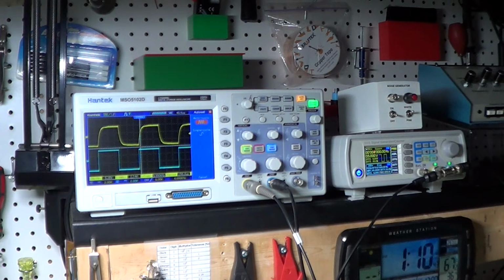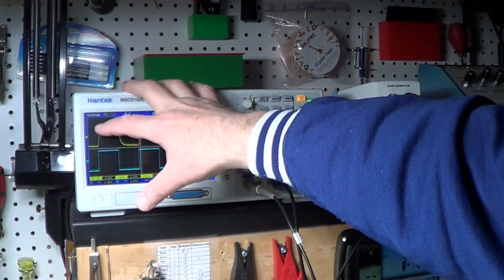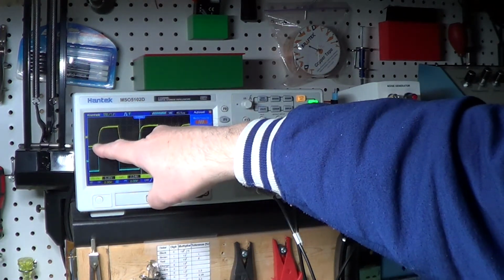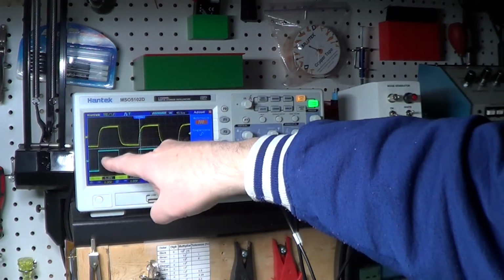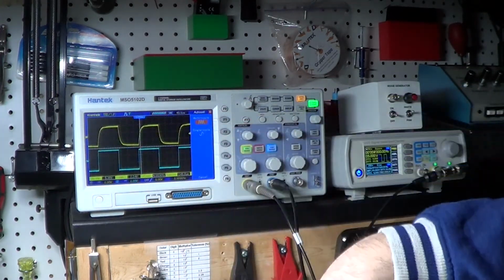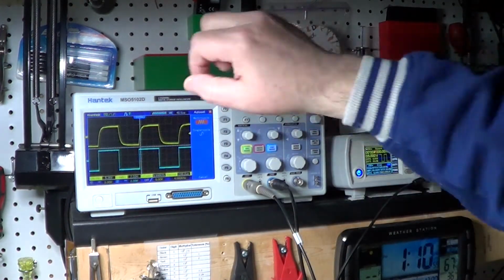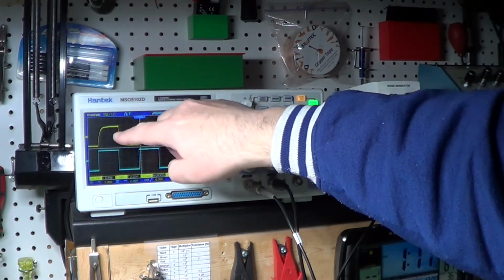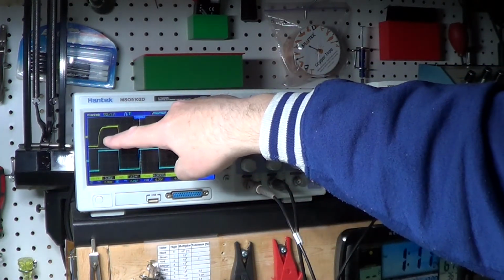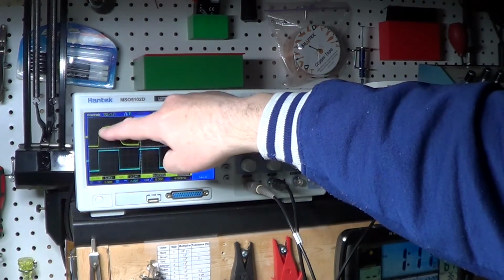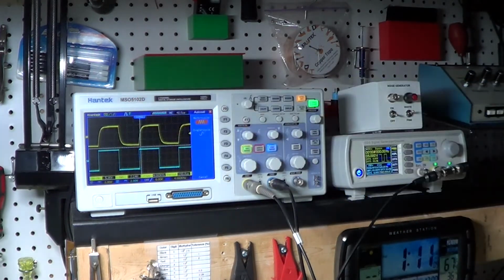Basically, when you see something like this, you know that you have in front of you a low-pass filter. There are high frequency components that allow the signal to come straight up like in the input over here, but the filter is removing those high frequency components, and so the square wave at the output of the filter gets smoothed out like this when it goes up, and like this when it goes down.